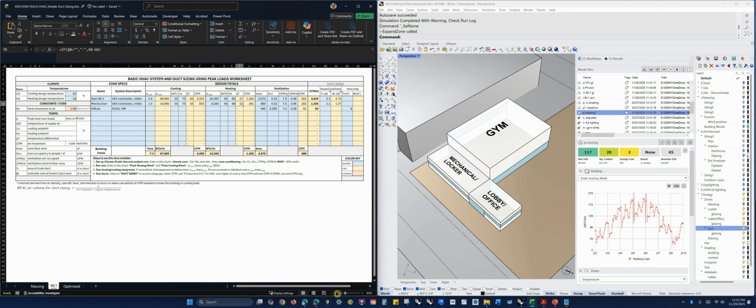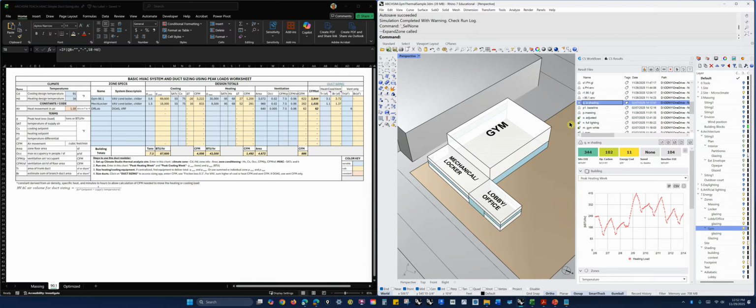So I've run a baseline. I started with a really bad envelope, like a 1960s all concrete, no insulation, single pane glass, not that great of a mechanical system. I typically do that to start with something and improve on it. And then I went through 90.1 optimizations, and then I used what I know about how I could improve the envelope to a Passive House level and Passive House infiltration. My point is that I've already optimized this to some degree.